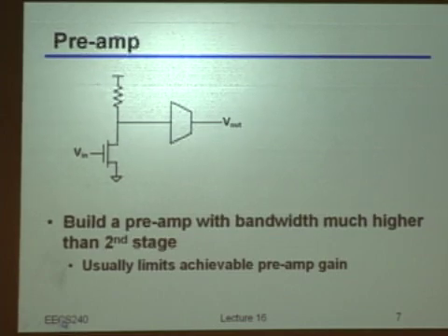So if I had an amplifier with a certain transfer function, which is again maybe just a one-pole transfer function, and that's my A, the idea is I can boost the gain a little bit while still having good phase margin by using some preamplifier.